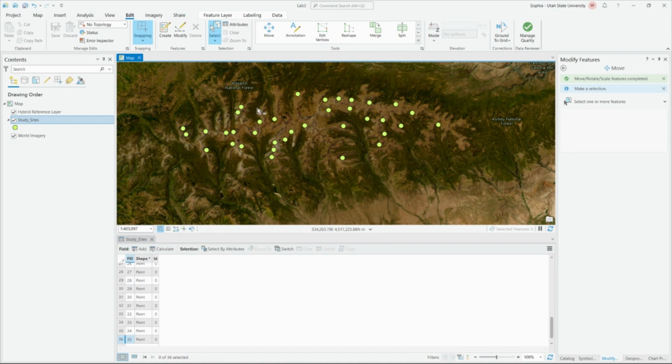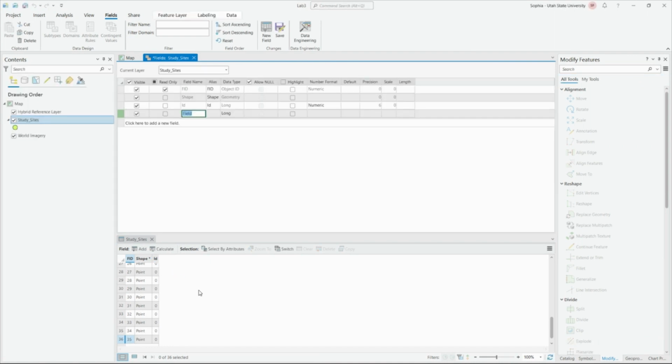So we're going to name all of these sites to make it easier to work with them in ArcGIS. So to come here to the attribute table, we're going to add a field. Quick thing to note, if this is grayed out when you try to go add it, that means you haven't saved something up in the edit when last you were editing your data. But we did edit, so now we are here. We're going to name this field site name.